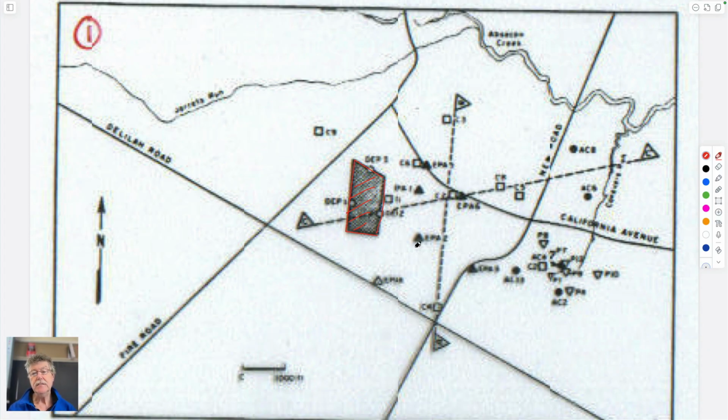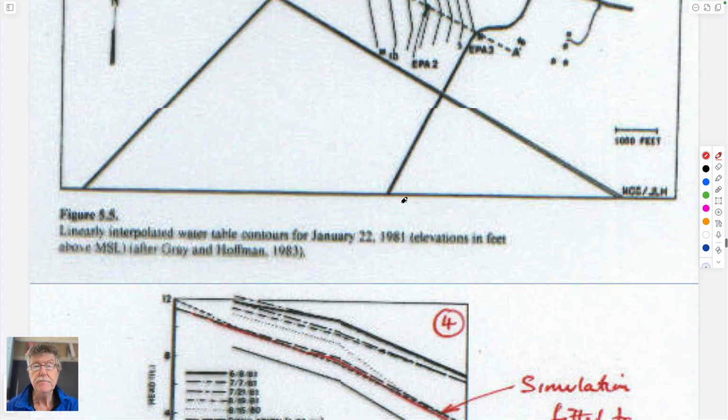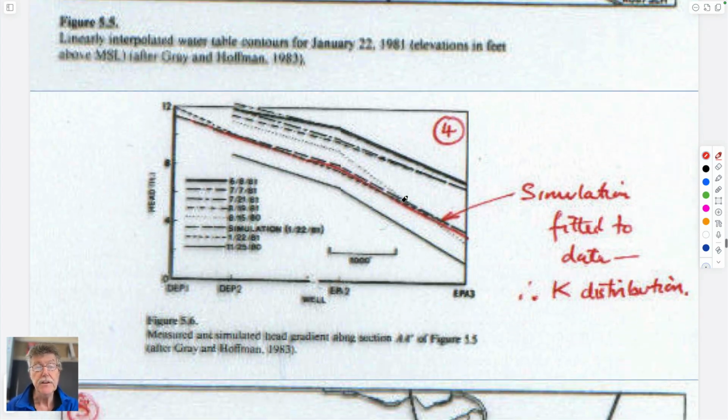And so the idea is that if you put in some wells and try and draw some hydrologic cross sections for the water table along these two different sections, you can find out where the main pressure water table drop is. If the water table is flat, it means that the main drop must be orthogonal to that. And so you could plot out the water table along a number of sections, and that would be exactly what this is.